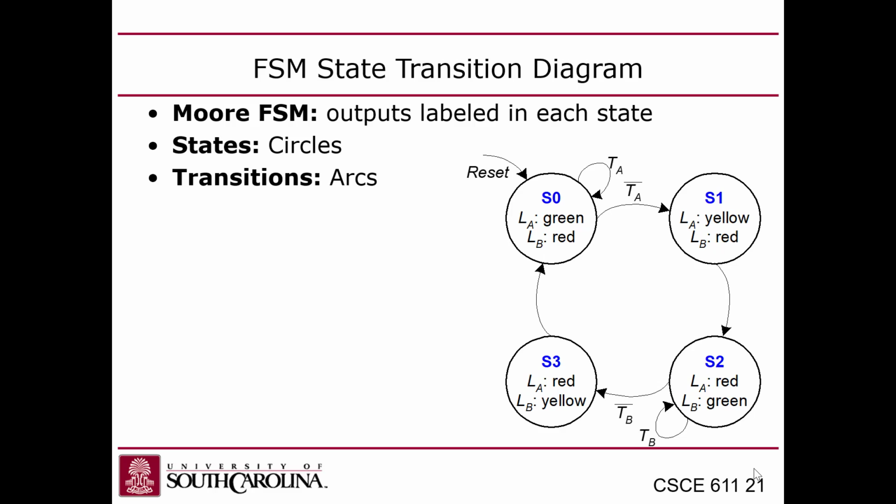In most cases, at least in my experience, it's common to just design state machines as Moore style, right? The way I always thought of it, the way I remember the terminology, was Moore is less, in the sense that a Moore machine has less complexity than a Mealy machine, which is a little bit more complex because the output logic involves both the state and the inputs, as opposed to just the state.